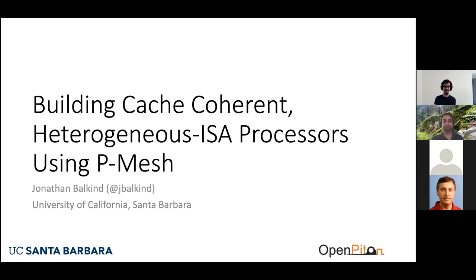I don't want to give away too much, but this is something that we've been actively working on. It's definitely doable, and it would be really cool to be able to put a core or something else on that fabric. There's a question of how you provide an interface into your cache coherence system, but then the FPGA can't just do whatever it wants and break the rest of your system, right? So there are questions that have to be answered in that space.